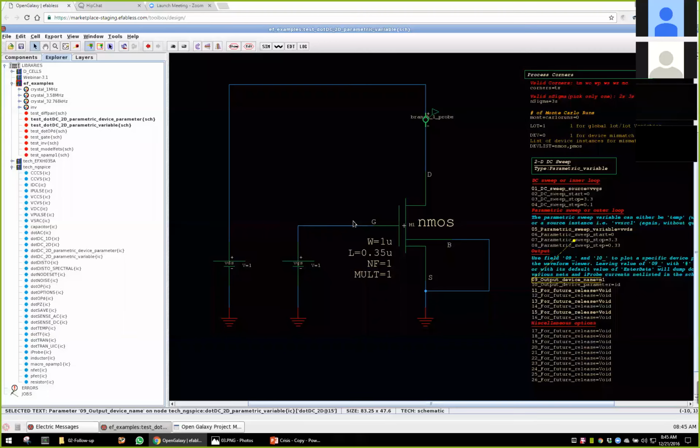So if you want to be creative, you can add all the NMOS devices from the PDK for this challenge in parallel and do this ID versus VGS for varying VDS. And you can compare how these unique devices, every NMOS or NMOS RF, performs. You can stack these two guys against each other and see their performance and decide which device to go with. I know NMOS RF is not good for analog, but there might be something worth looking at.